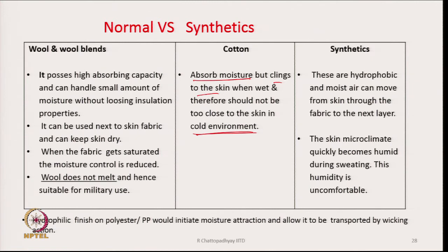especially in military situations, the wool is not going to melt, whereas polyester or any other synthetic fiber is going to melt, and the fabric is going to stick to the skin, and that will give a lot of burning sensation to the wearer. So, that is the danger that we have in such situations, whereas wool will be quite good in such situations. Wool, we all know, is a self extinguishing fiber, and that is the best part of wool.